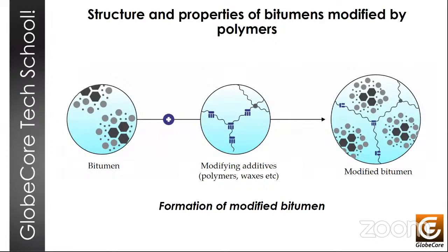In bitumen polymer mixtures, both dispersed phases, that is asphalt resinous substances and added high molecular polymers, compete with each other for a dispersion medium. Styrene and butadiene are compatible with aromatic and non-aromatic components of bitumen respectively. And it is this property that explains the strong interaction between SBS and bitumen. Butadiene blocks mixing with bitumen swell and absorb a significant part of the maltenic fraction, while polystyrene blocks, less compatible with bitumen, fall apart into isolated domains, thereby providing positions for lateral links.